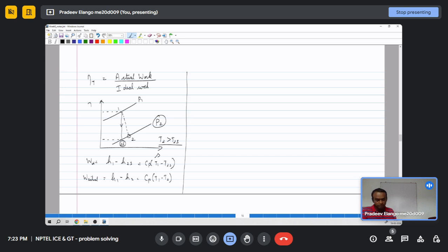So this difference in actual and ideal case of the turbine, like how we deviate from the isentropic process, is given by the isentropic efficiency, eta T. This is different from the Brayton cycle efficiency that we have been discussing. Are you able to follow? Yes, sir.